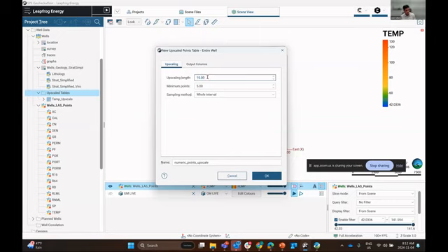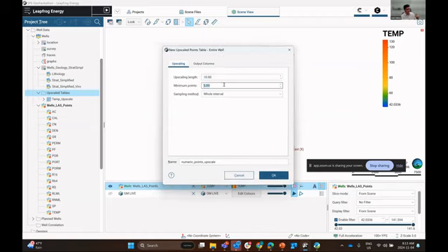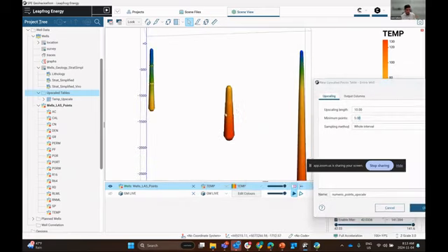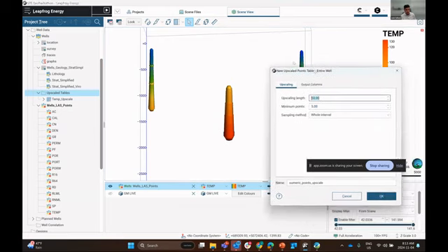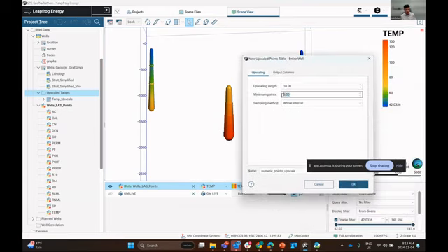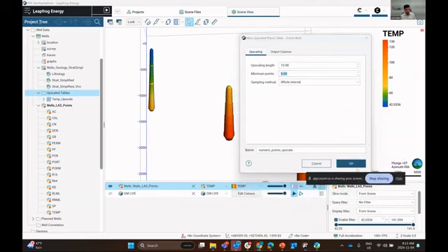This upscaling length shows the length, so 10 meters essentially, and this is going to average the values associated with each 10-meter interval along the well track with a minimum of 5 points. So all of this very densely sampled data will be averaged along an interval of 10 meters, but there has to be a minimum of 5 points associated with it.